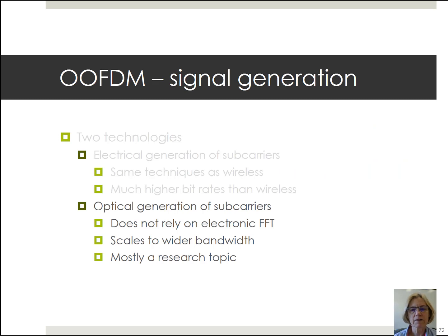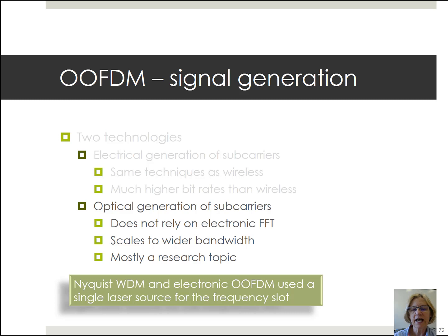So far I've talked about the electrical means of generation of subcarriers, and now I'd like to talk about the optical generation of subcarriers. In order to appreciate that, I just want to highlight again that the previous solutions, whether Nyquist WDM or the electronic version of generation of optical OFDM, in each case used a single laser source for the frequency slot that was being used. Now I'm going to contrast that with the solution of optical generation of subcarriers.